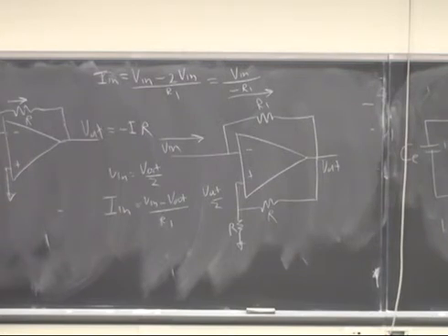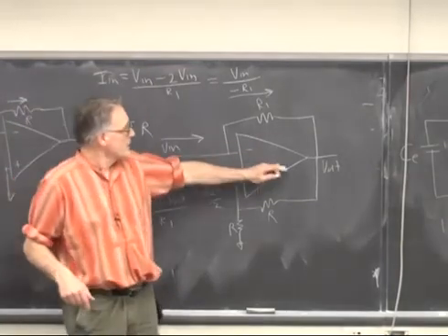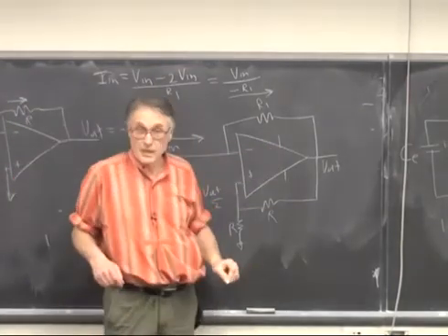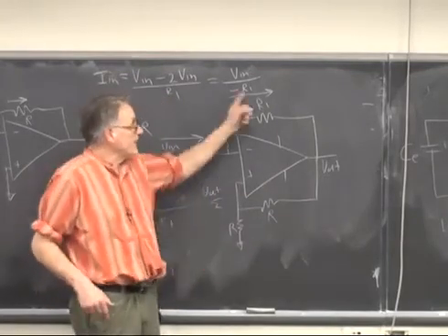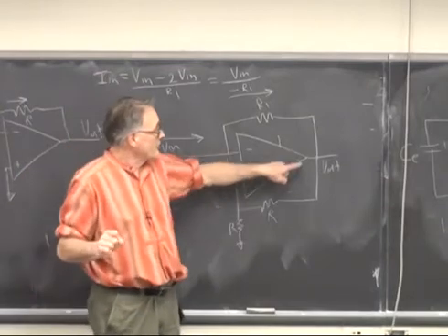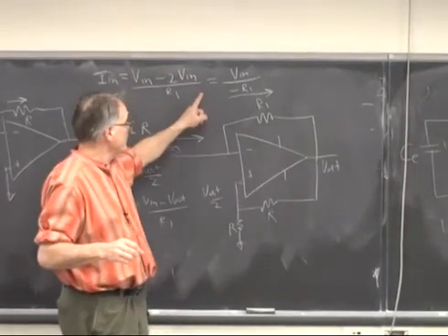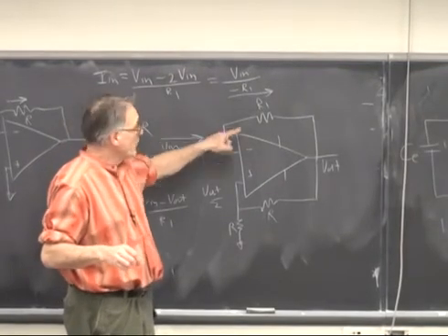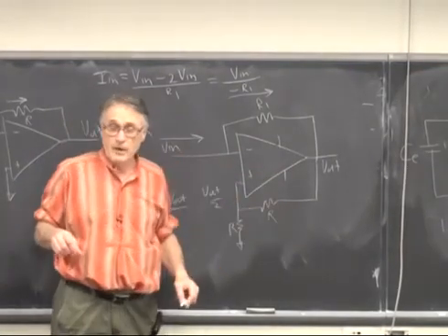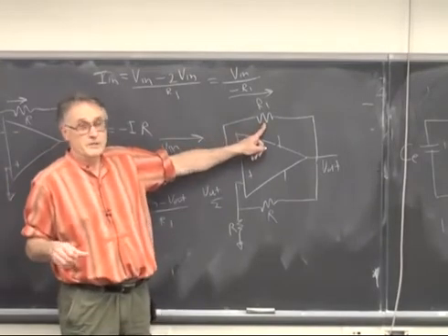But you don't have to conserve energy here, because whatever energy is necessary to make this happen comes in through the op-amp power supplies. And you only get a negative resistance so long as the op-amp can follow the voltage appropriately to force V out to V in. Once you get outside the range of the op-amp power supplies, then this goes back to being a regular old boring positive resistor.